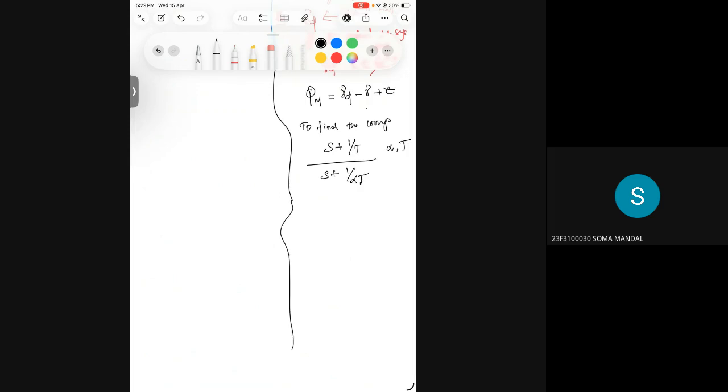The next formula is to find the alpha. That is alpha is equal to 1 minus sine of phi m, where phi m is the deviation you found here, divided by 1 plus sine of phi m. So if you know your phi m, you will be able to calculate your alpha. So we have solved one riddle, that is alpha. The next riddle left is your t.